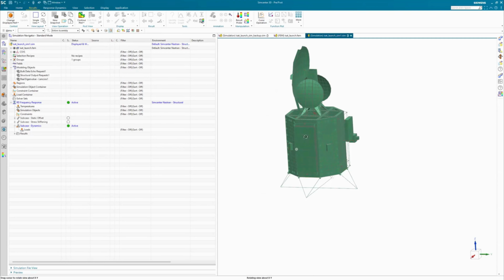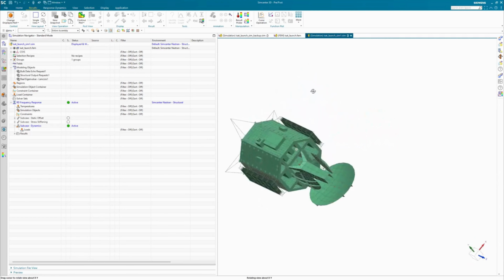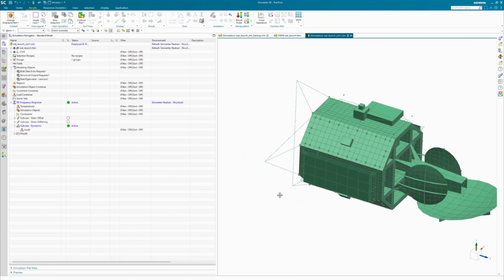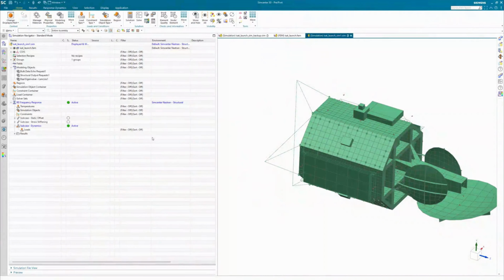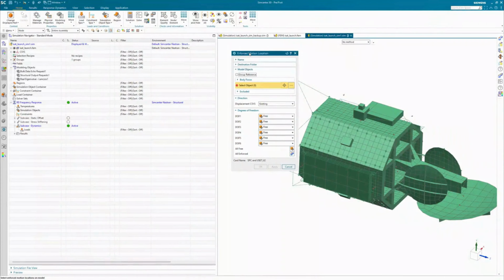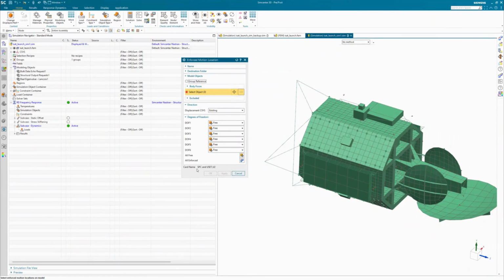The next thing we need to select here is telling Nastran where we want to apply our enforced motion constraints. In order to be able to apply those enforced motions in Simcenter response dynamics, we're going to need to enable those within the Solution 103 run. So we'll go up to this constraint type and add in an enforced motion location. This will generate cards that create SPC constraints as well as add the degrees of freedom that we select to the U2 set.